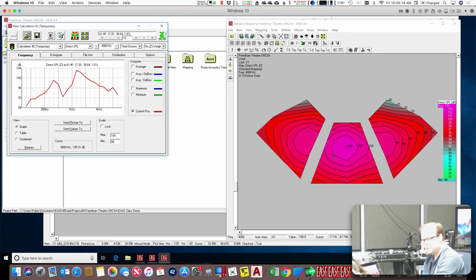But the main advantage of Ease and Laura was that it was no respecter of manufacturers, basically. It would let you plot systems that included loudspeakers from multiple manufacturers, which is difficult to do using the manufacturer-specific plotting tools. Meyer's MAPP only lets you plot stuff that Meyer makes. D&B ArrayCalc only lets you plot stuff that D&B makes. And honestly, it's only the stuff they've made in the last 10 years that you can put in ArrayCalc, because they want you to buy new stuff, and so they're not going to make you very comfortable using old stuff.